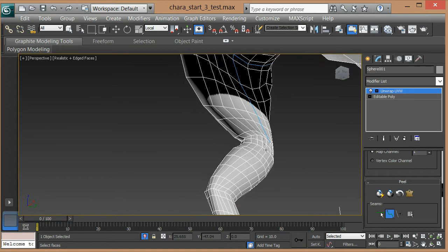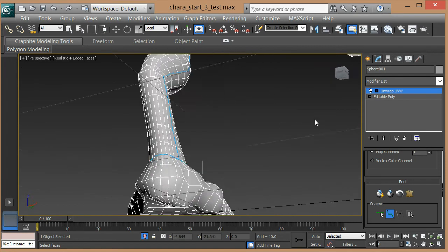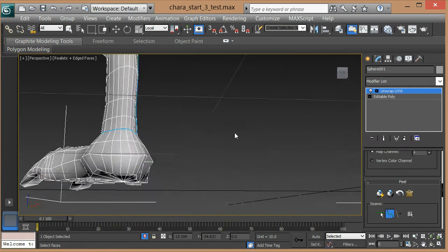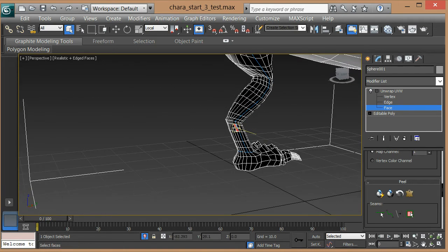I'm working in a really small space because my screen capture software is running behind, therefore it's a bit hard to see. Okay, now I direct the UV seam over here. Then I go to the face, click one face. Under the UV, make sure you exit this point to point seam by clicking it again.